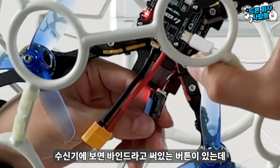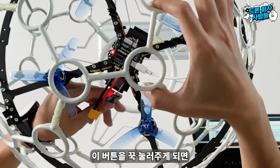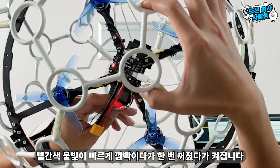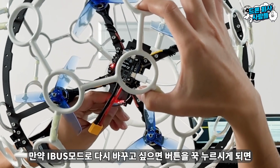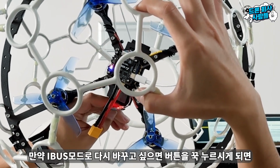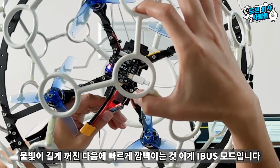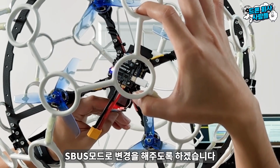On the receiver, there is a button labeled bind. If you press and hold this button, the red light on top will blink rapidly, then turn off and on again. This indicates S-bus mode. If you want to switch back to I-bus mode, press and hold it. After it turns off for a long time and then blinks quickly, that's the I-bus mode. Since we will be using the S-bus mode, we will change it to S-bus mode.